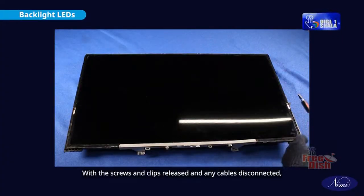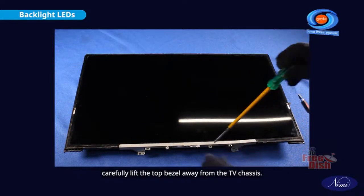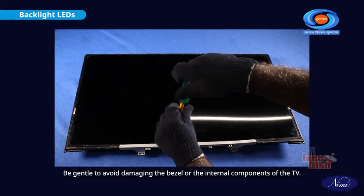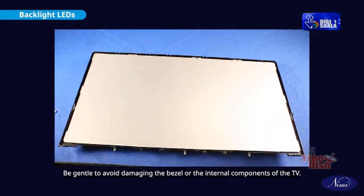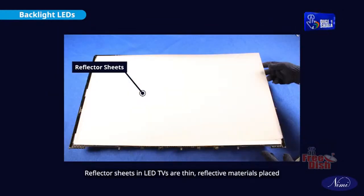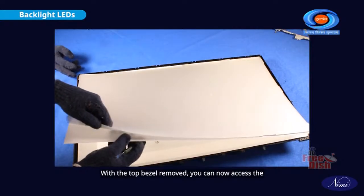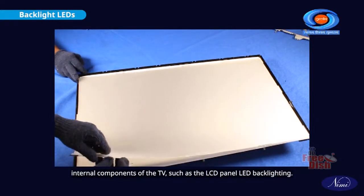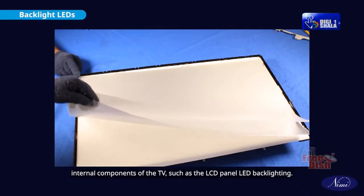With the screws and clips released and any cables disconnected, carefully lift the top bezel away from the TV chassis. Be gentle to avoid damaging the bezel or the internal components of the TV. Reflector sheets in LED TVs are thin, reflective materials placed strategically behind the backlight LEDs to improve light efficiency and uniformity. With the top bezel removed, you can now access the internal components of the TV such as the LCD panel, LED backlighting.